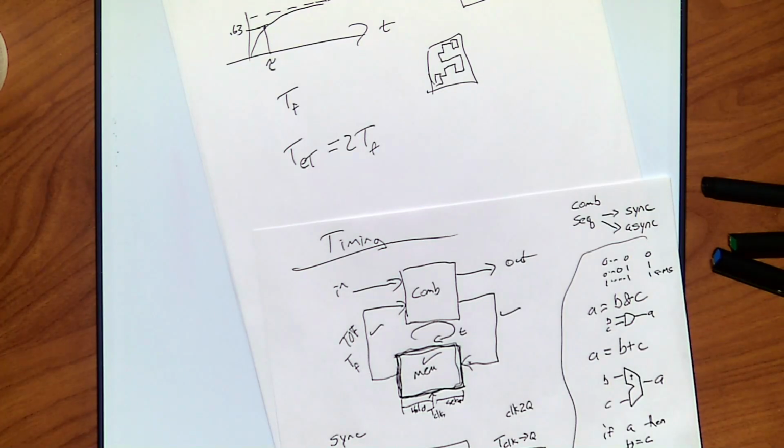The number of wires needed to go into a gate for a ripple carry adder is constant. Right? You only ever need 2 wires to get into those gates. If you go to our conditional sum, it'll get up to log 2 of the number of bits going into the gates. So that still puts me in 6 to 8. That's a reasonable range for most logic to handle.